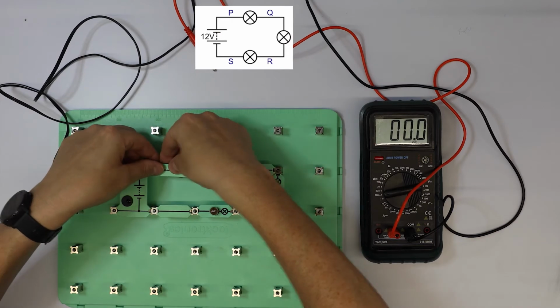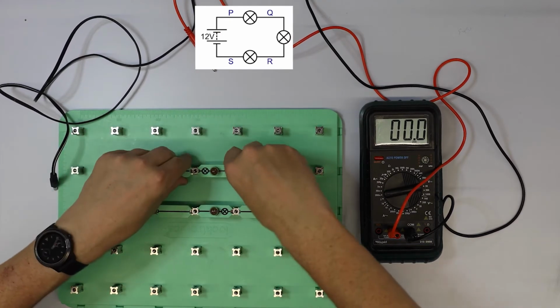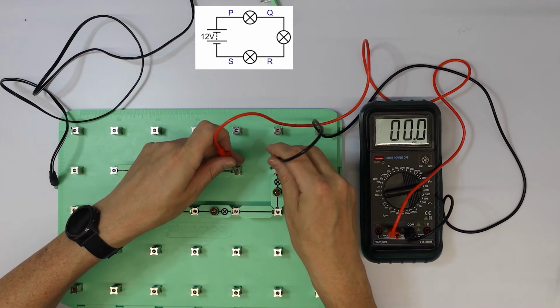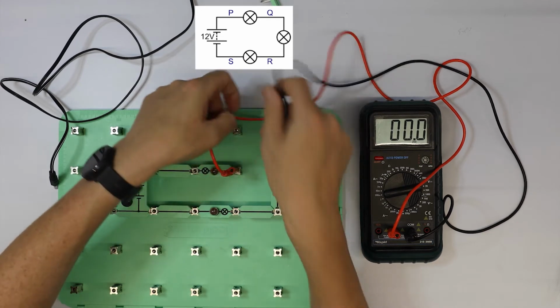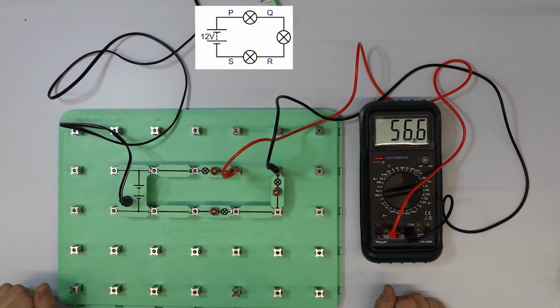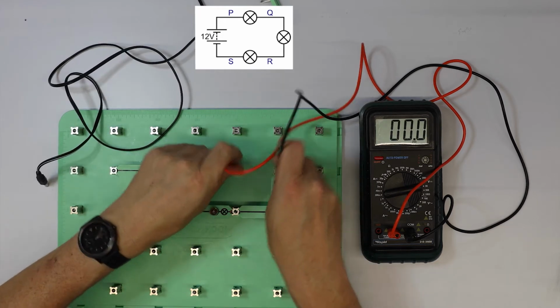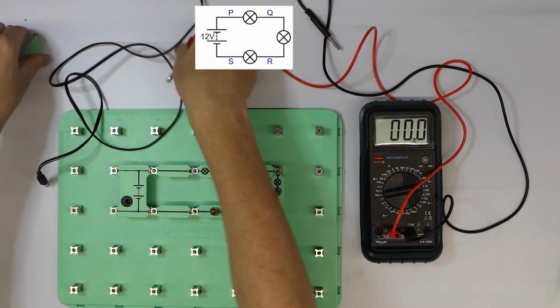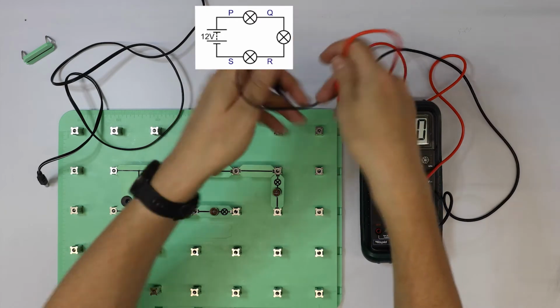So now I'm going to remove those leads again, place back my linked lead there, remove this link lead, and put my next leads in the next location. Connect the power supply, and I'm getting a very similar reading. This is 56.7 milliamps. So it's pretty much the same current that we saw at the previous point in the circuit. So once again, take out the leads, take out the link, and replace this link here at point R.